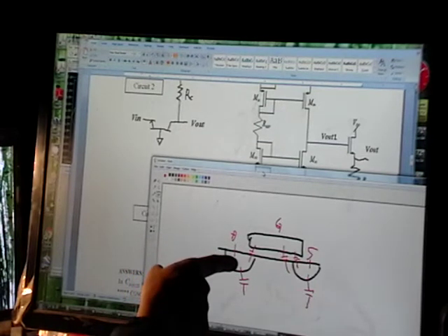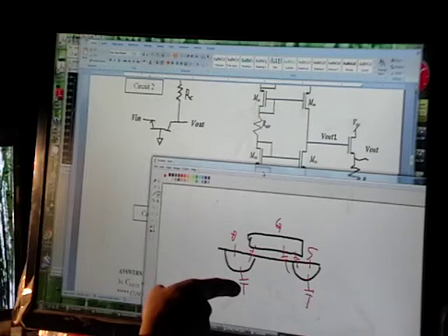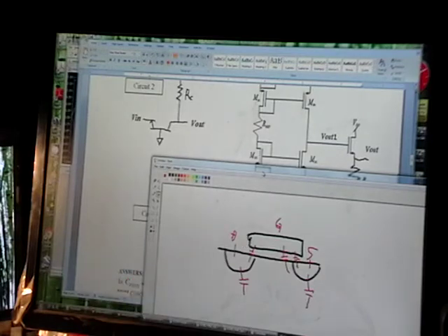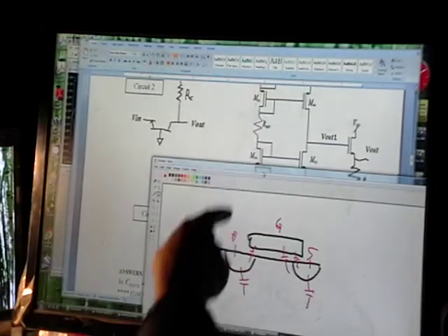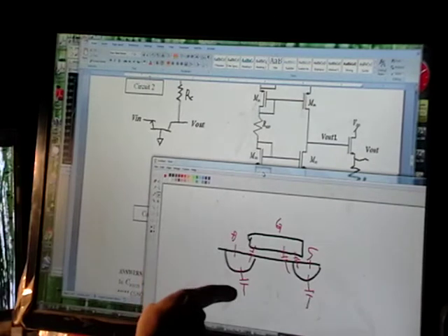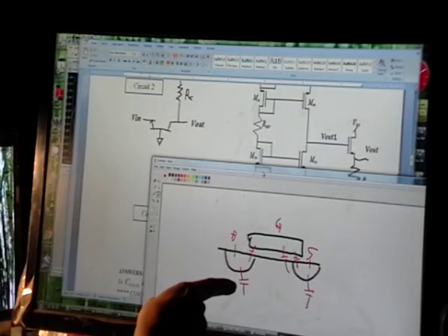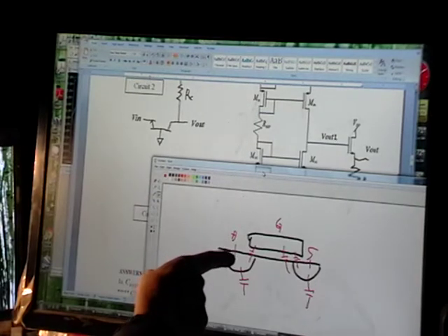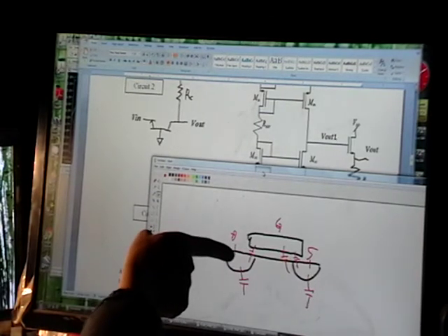You see the drain to substrate, or drain to bulk, so dB. You also see the gate drain overlap. So the capacitance looking up would be gate drain overlap and drain bulk. Okay, looking down, you hit another drain. So again, you're sitting here and you see what capacitors you see if you're sitting on the drain.